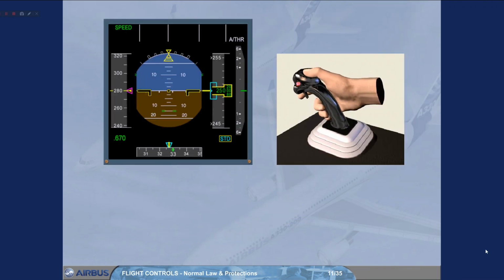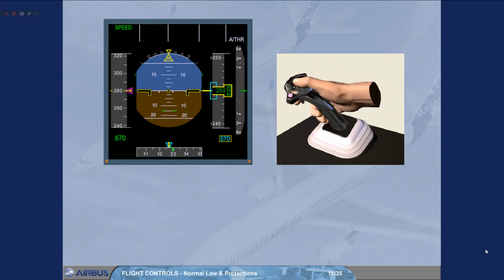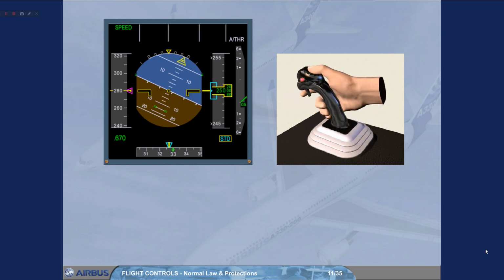In flight mode, if you wish to execute, for example, a descending left turn, you set the required attitude and then return the side stick to neutral. The neutral side stick position asks for 0 rates of pitch and roll. The flight control computers will maintain the set attitude until you use the side stick to ask for an attitude change. Throughout the maneuver, there are no pilot trim inputs.